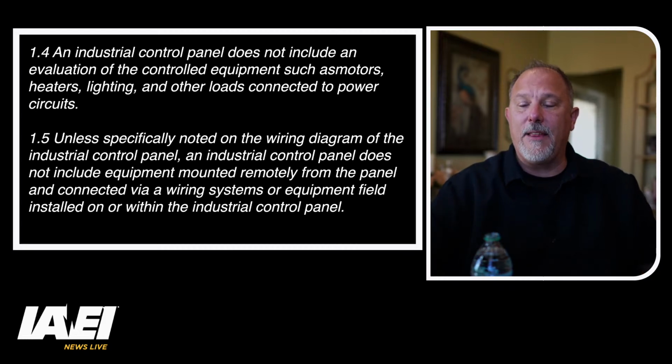When I first read it, I read it wrong. That has happened before, and it will happen again. So, dear God, CMP 11, yes, please. What's interesting is you have to have two or more components, and one of those components has to be power circuit components only, such as motor controllers, overload relays, fuse disconnects, and circuit breakers.